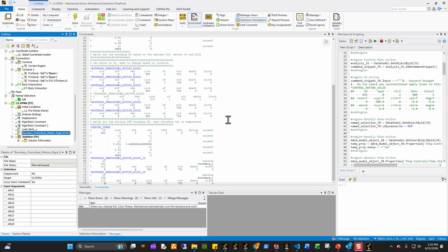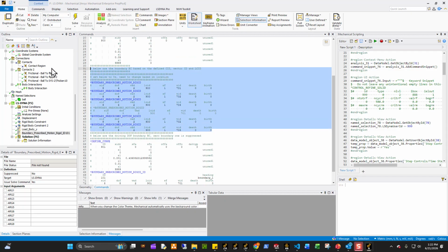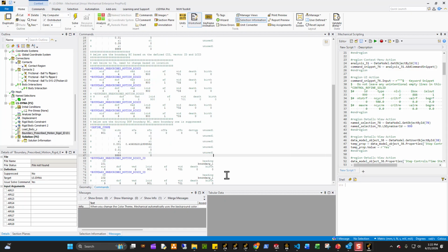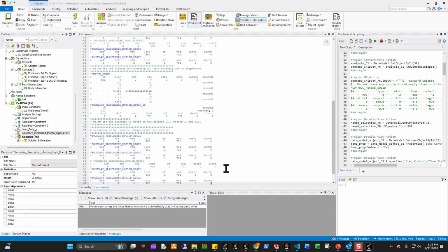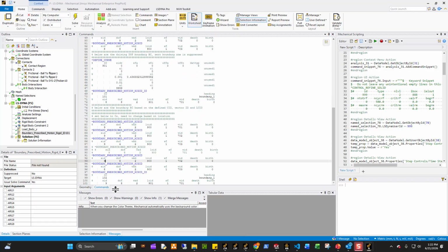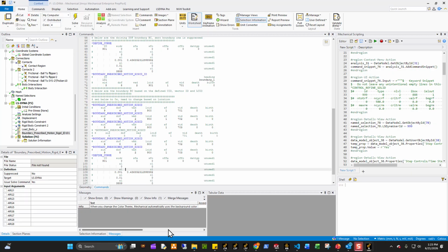So in this case, I actually have to do this. Hold on one second. I'm going to create another set of constraints, and in this case I'm going to do 9, 9, 9, and that's going to constrain flipper number 2, which has an ID of 9. It's going to call out the same load curve. Actually, I'm going to call out a different load curve, because it has to be in the opposite direction, since the flippers flip in opposite directions. This one will have a negative number that we want to assign, and that's essentially what's happening here.